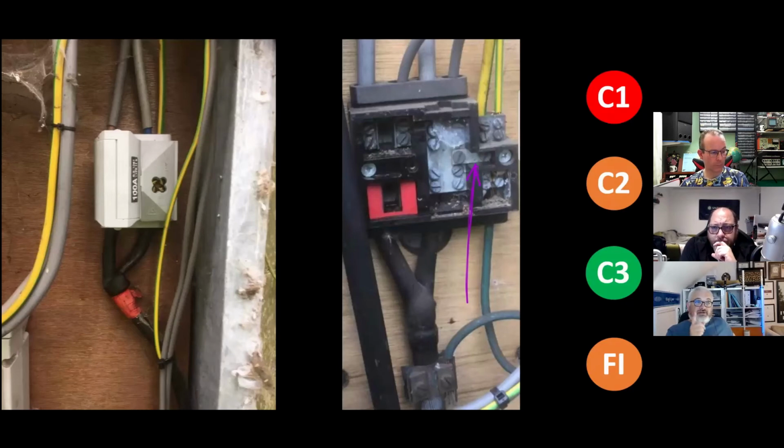And I worked on a lot of these for many, many, many years. And these used to confuse the hell out of me until I went on the training and somebody said that cutout can be used for TNS, but it can also be used for PME. It all depends on if they have a separate earth cable that comes up on the right, which as you can see, they did. You can see here the green coming off the armor, coils round in a helix, goes up into the earthing stud, for the earth connection. So naturally, you could assume it's still a TNS with just a facility of an earth terminal built in. But that link now makes it a PME.